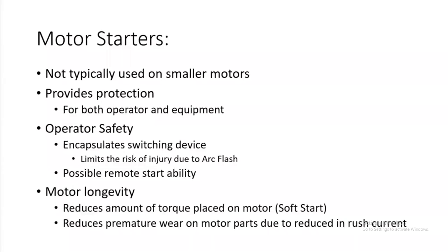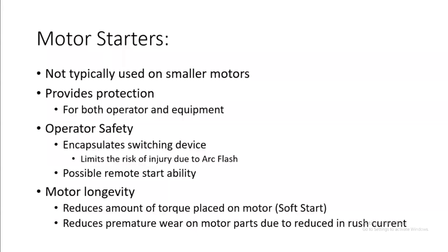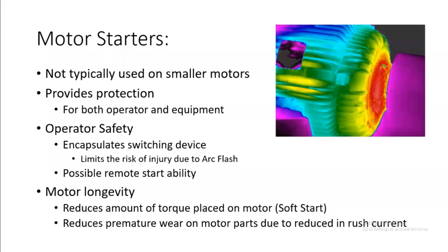When a motor is started, there is typically a large inrush of current. This inrush can put a lot of torque on the motor and other motor-related hardware. Also, the inrush of current can prematurely wear out and cause early failure of the motor because of the stress created on the hardware within the motor itself.